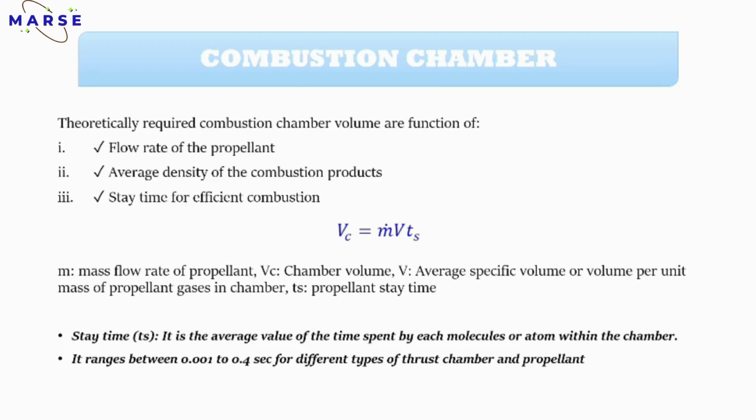Stay time, I have put the definition of it also: it is the average value of time spent by each molecule or atom within the chamber. What it means is there are so many molecules randomly moving in the combustion chamber, right? So the stay time means the average value of the time spent by each molecule or atom within the chamber.